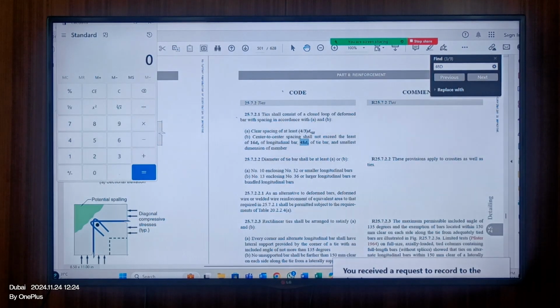Complying is different. For example, in terms of site, whether you have executed all the reinforcement. Do you think it is easy to go again and fix the rebar at the bottom layer, top layer? Imagine 12 layers. The starter bars are already fixed, you already provided 4 bars, and you already got the approved shop drawing. Authority is authority, right? They'll come and ask you anything. They'll ask you to fix. If in case they ask you to fix, how difficult it is for all the columns. Making the stirrups is one challenge, execution is another challenge.